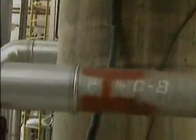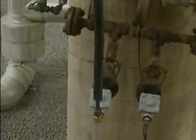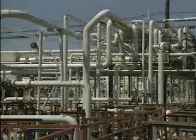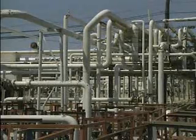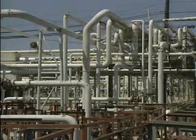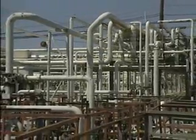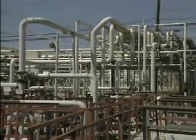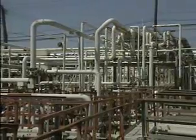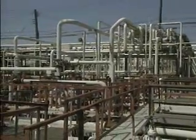Under low temperature conditions, condensate can freeze in piping, resulting in damage such as burst pipes and costly shutdowns. Accumulated condensate can also cause water hammer. Water hammer is the condition that occurs when condensate is carried along with the steam inside a system's piping and slams into the wall of a pipe, particularly around bends. This action can break or crack the pipe.